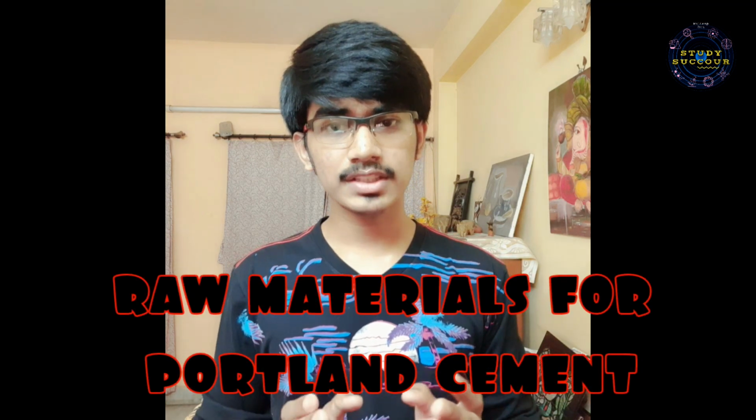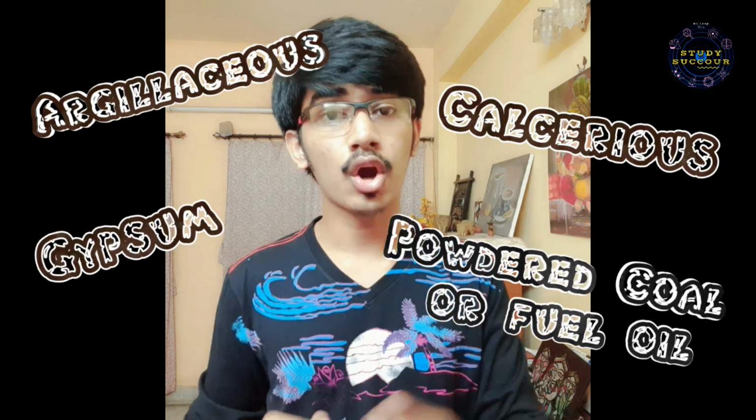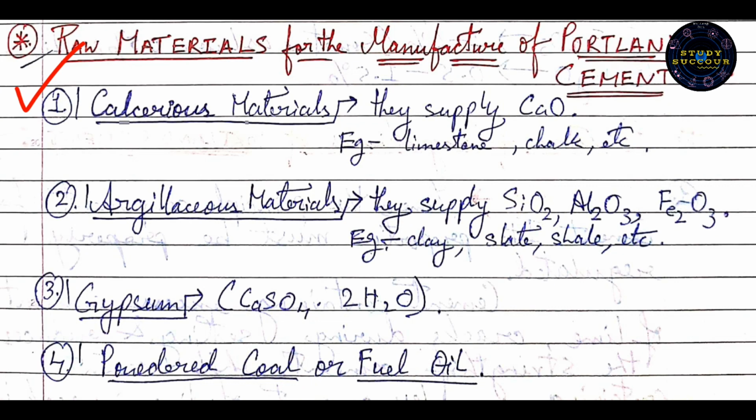Now, raw materials for the manufacture of Portland cement are, as discussed earlier, argillaceous materials, calcareous materials, then comes gypsum and powdered coal or maybe fuel oil. Here, calcareous materials supply CaO or calcium oxide, for example, limestone, chalk, etc. Argillaceous materials supply SiO2, Al2O3 and Fe2O3, that are silicon dioxide, aluminium oxide and ferric oxide, for example clay, shell, slate, etc. Now gypsum, that is CaSO4.2H2O, calcium sulfate.2H2O, is itself a product. Then comes powdered coal or fuel oil, which is used during the burning purposes.